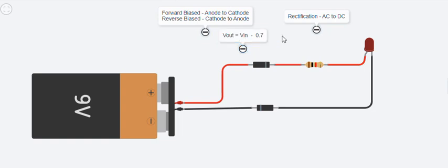Do you understand? Yes. It depends on the kind of material that was used in making the diode. Sometimes it can be a germanium diode. If it's germanium, it has a certain amount of voltage that goes away. Other components have their own, but generally we take 0.7 just for theoretical understanding.